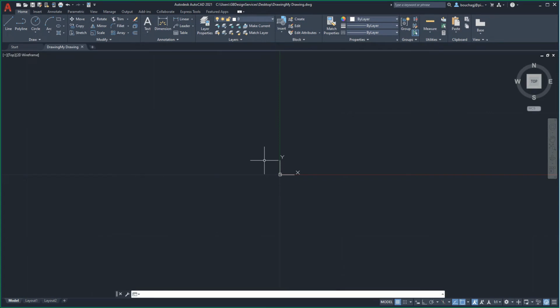Ideally, each user will have in place a file management system for organizing and keeping track of drawings and project data. Once we complete the steps of modifying the drawing settings to our own personal preferences, we will then take the opportunity to save this personal file as a drawing template file, a file with a .dwt file extension, and place it in the AutoCAD templates folder.